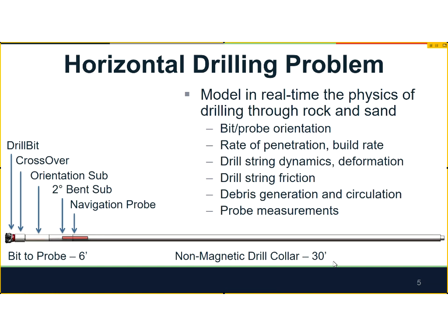And so this equipment here, in this scenario, is basically a fixed piece of equipment that they would use in drilling in sand, for example, in a jetting. So they basically have a jet, and force about 300 gallons per minute of drilling fluid out of this hole, and it blows out the formation in front, and then the debris gets circulated behind the drill pipe.